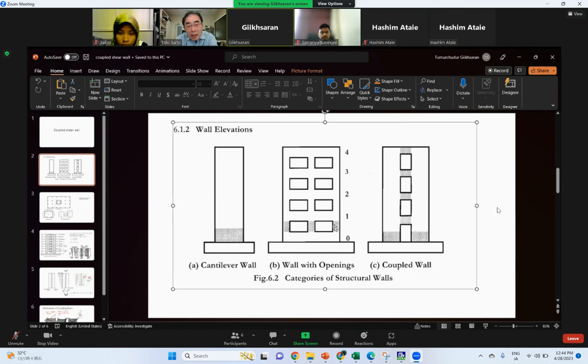Generally below the first floor, as indicated by the shaded area, it is very difficult to avoid inelastic action occurring by flexural yielding or shear failure in the piers.